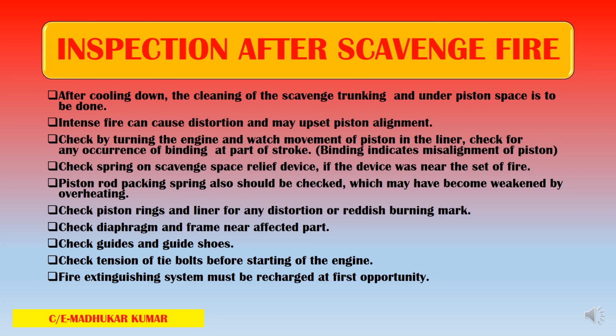Check the diaphragm and the frame near the affected part. Whichever unit has been affected, the diaphragm, frames, everything has to be inspected. Check the guides and guide shoes of that particular affected unit. Check the tension of the tie bolts before starting the engine, because overloading, overheating and fire can cause anything. So it is better to check the tensioning of the tie rod bolts.